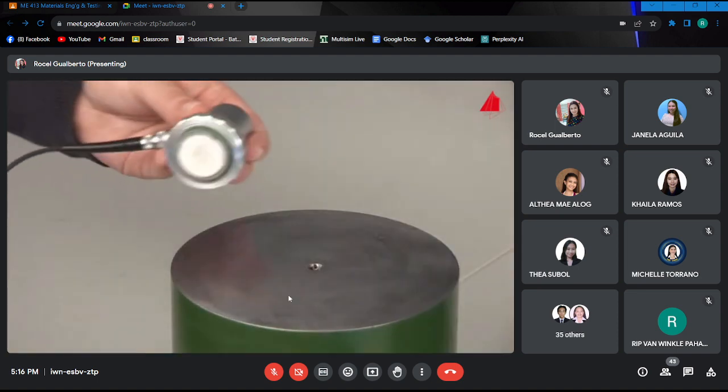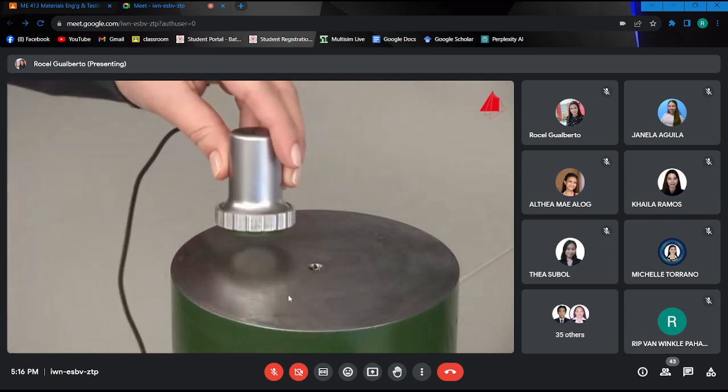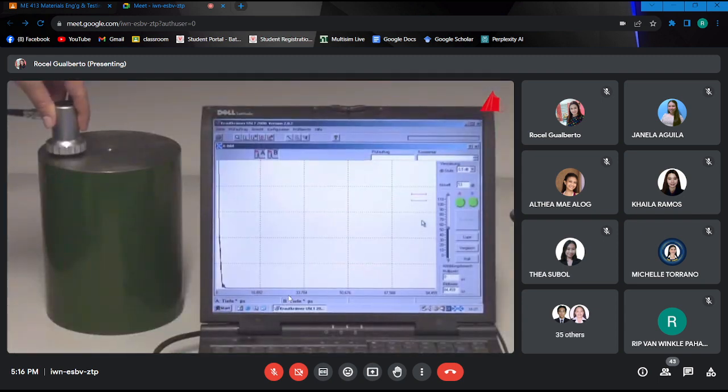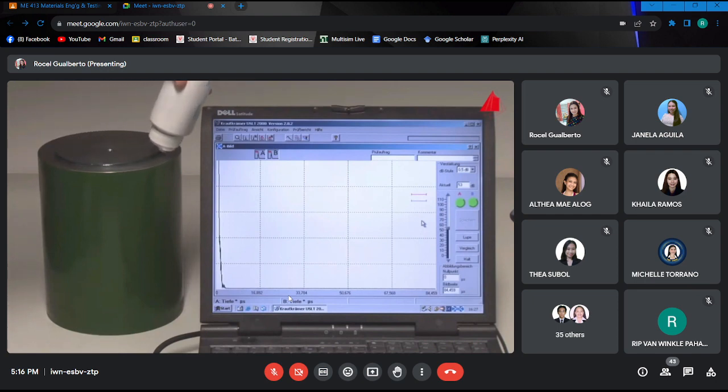After placing the probe on top of the cylinder, initially no echo at all may be seen on the monitor. The reason for this is the too small contact area between the probe and the workpiece. Only with the use of a gel, the so-called couplant, the ultrasonic pulses can get into the workpiece and can also go back into the probe. Now the back wall echo turns up on the monitor.